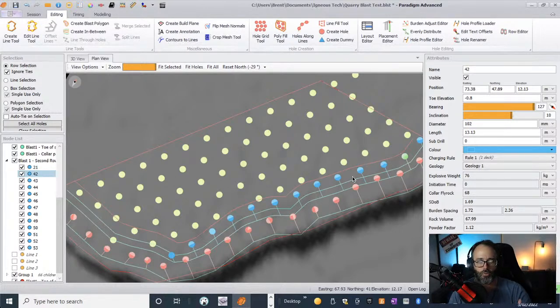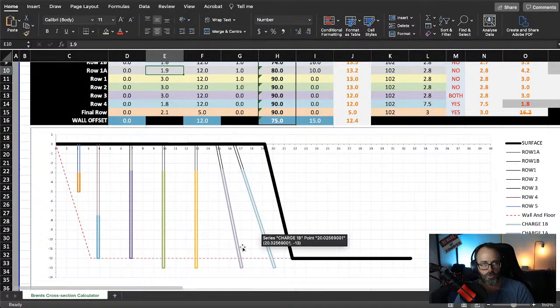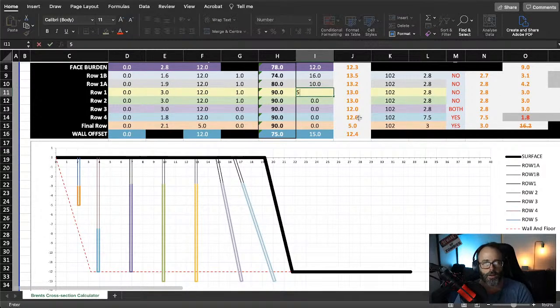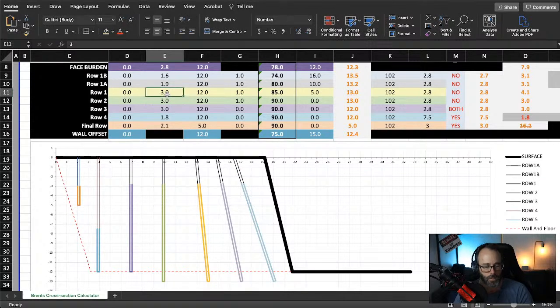But as you can see, with slow progression of angles, you need to do it very considered. And in this case, with progression through these angles, you need to slowly increase the angle, because as you can see, like we said, this is 4 meter separation, 4.2. So we would need to consider this next row at 5 degrees, and that way we can then compress this only a tiny bit. So that's at 3 meters, but this 3 meter collar now can come down to 2 meter collar separation. So you know, that might be 2.